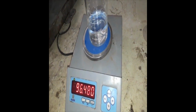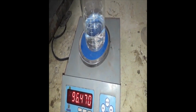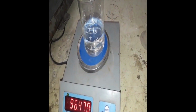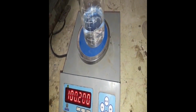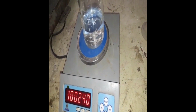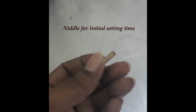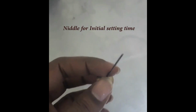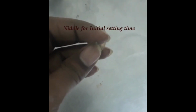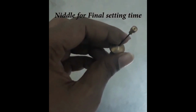Now the accurate measurement of water is very critical in this case, because as we have already understood in module 1, the water reaction with the cement defines the strength of the cement. So be very precise when we are calculating the volume of water. If water is added in more quantity, then the strength will reduce, and if the water is added in less quantity, then the proper hydration will not take place, and again the strength of the cement will reduce. Hence, to gain the maximum strength, the accurate quantity of water is a compulsion.